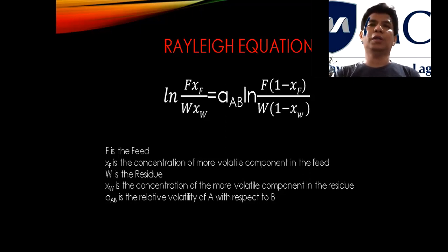Unfortunately, if you're going to use the 2 equations, the overall mass balance and the alcohol balance, you will only have 2 equations. So you cannot solve the other variables. For example, you can find how much lambanog are you going to produce before you stop the distillation? You won't be able to calculate D. Pero with Rayleigh equation, you will have three equations and you can solve D, or the amount of lambanog that you're going to produce before you stop the distillation. Okay, so that's the practical application of the Rayleigh equation.